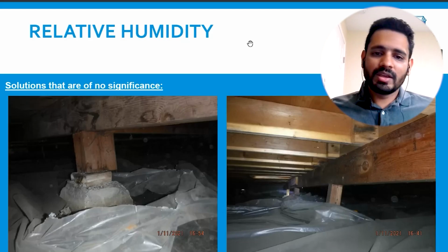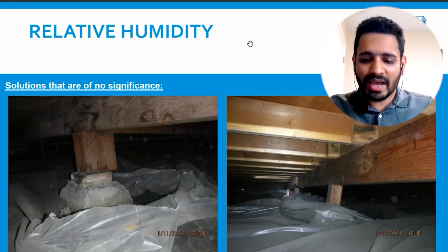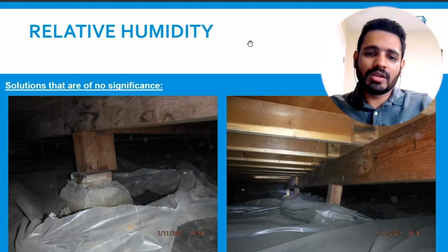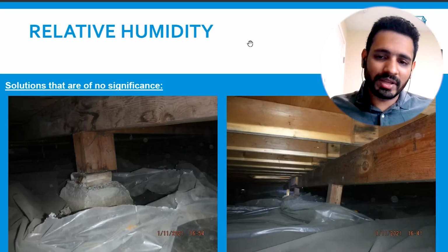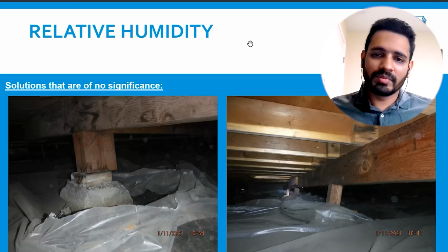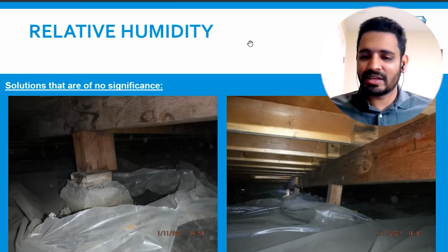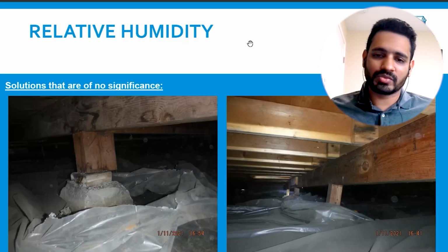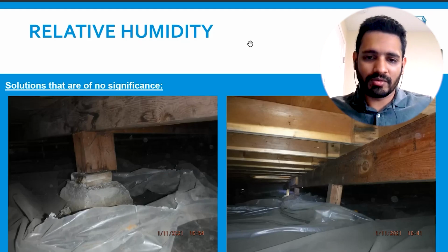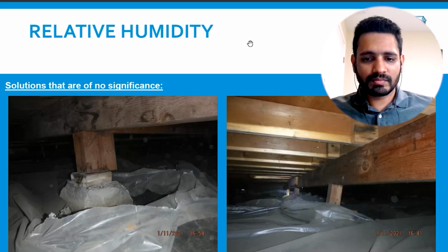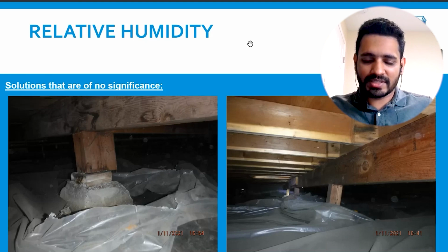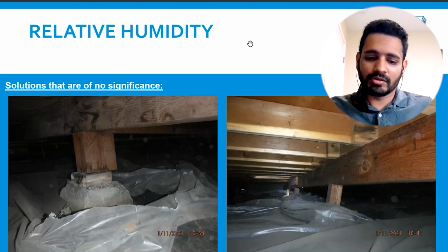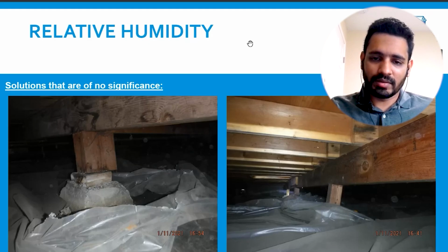in the Bay Area. And any of those things, when you have that happening in an excessive fashion, you would find it resulting in some kind of an issue. So we try to monitor and control and mitigate these interactions as much as possible to minimize or slow down the damage process. At the end of the day, water can find its way, moisture can still find its way somehow, but we try to stop it and slow it down. Basically, to regulate the relative humidity within the crawl space. Exactly. So that you can keep it in the acceptable range, or in your best case scenario, you can keep it under the optimal percentage of 40.